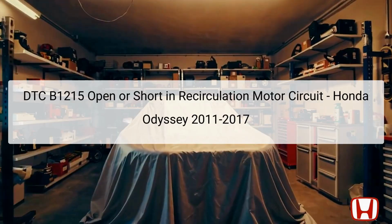The diagnostic trouble code, DTC B1215, indicates an open or short circuit within the recirculation control motor circuit in 2011 through 2017 Honda Odysseys. The recirculation control motor plays a crucial role in managing air intake in the vehicle's climate control system. This motor allows the heat and air conditioning systems to either recirculate the cabin air or bring in fresh outside air. It is usually located within the dash area, close to the HVAC, heating, ventilation, and air conditioning unit.